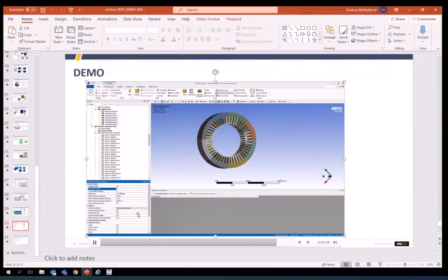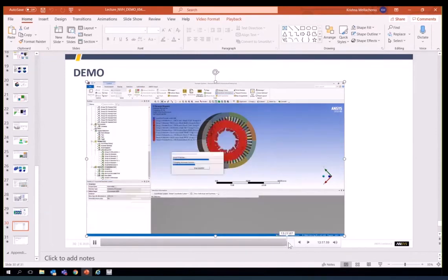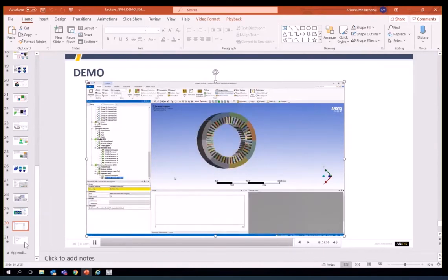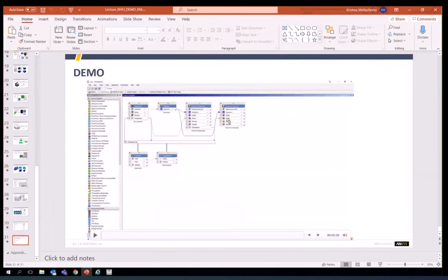Here is where we can change the number of RPMs, how many RPMs we would like to use, and then it'll have multiple imported remote loads folders for different RPMs. Using all of this, you can generate waterfall plots because it needs multiple RPM data to be able to generate these. So that's pretty much the overall workflow. You can then take this to acoustic response analysis as well, and map the velocities to perform the acoustic analysis and integrate everything at the Workbench level to do optimization studies. So this is the overall workflow for NVH.